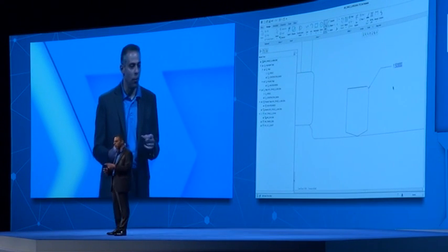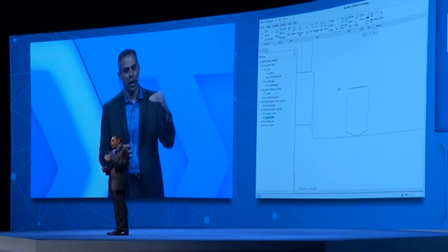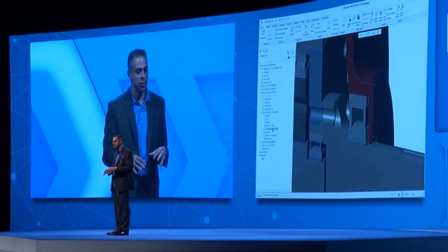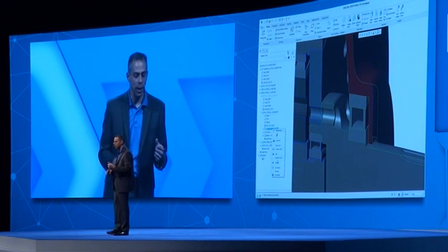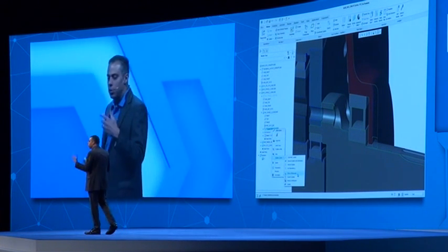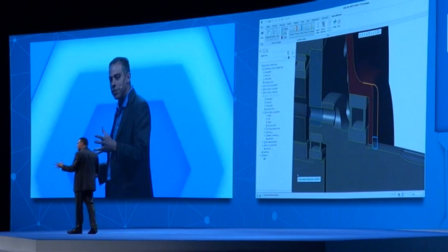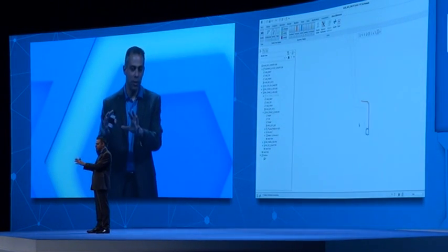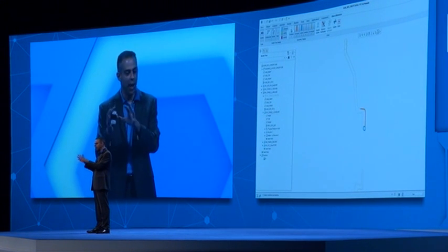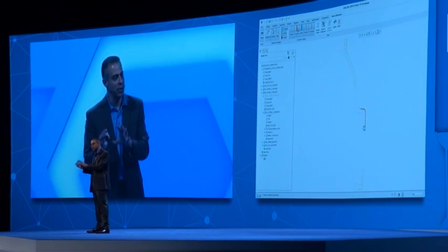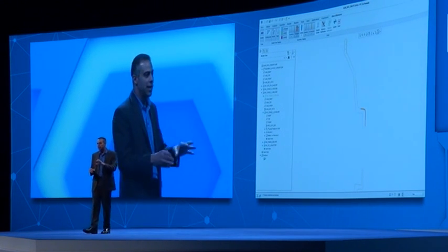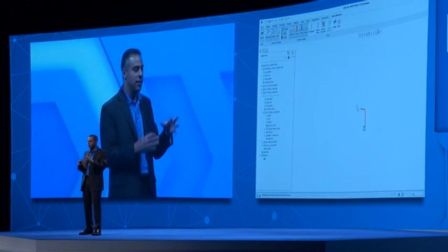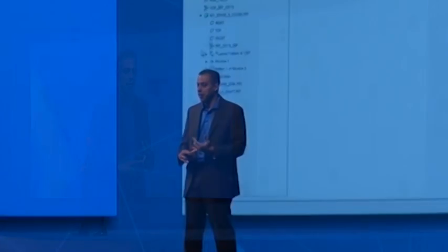In Creo 3.0, we're going to give you entity by entity updates on exactly what's changed in the 2D environment. So here you see I've got some outdated geometry, and I have this ability in Creo 3.0 to show the differences. I can actually see the differences before I accept the changes in Creo 3.0. And now what you see here is I have the 3D design engineer isolating just the changes that have occurred in 2D so we can investigate on an entity by entity level exactly what's happened in 2D before he accepts those changes. You can isolate things that have changed, things that have been deleted, things that have been added.